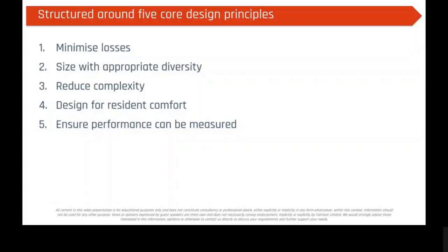Insulation applications that are inadequate, but then also insulation that's not installed correctly. So we have gaps in insulation, we have insulation that's too thin, and that's led to a lot of schemes with quite high heat losses, which obviously raises the carbon footprint of the system, but also raises the bills to residents. Things like overheating and resident complaints. So minimising losses is absolutely core to a successful heat network.